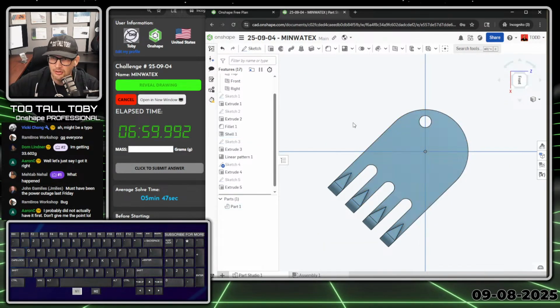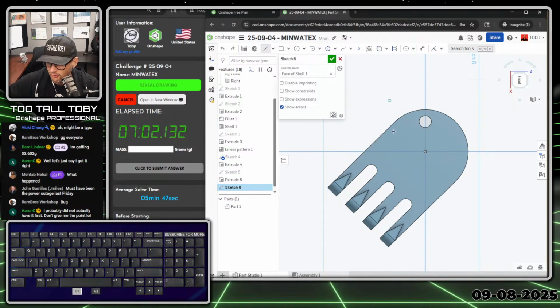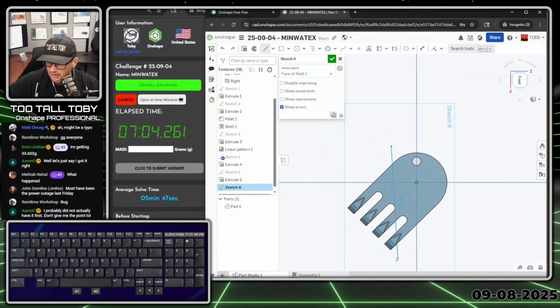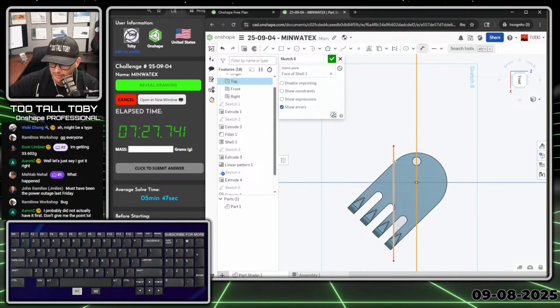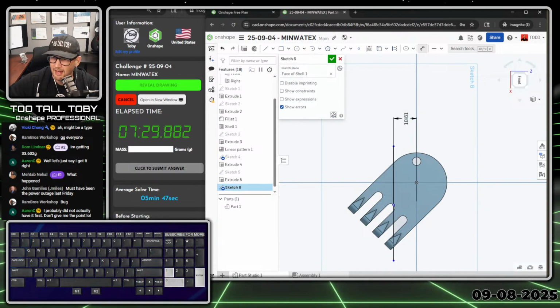this face here and I begin a new sketch and then I create a line there running along that face, then what I can do is take that line and add in a dimension. So the dimension could go here from this plane to this line. And oops, I didn't make the line vertical. Let me click on that line V. Let me click on that line H. I'm very disoriented in this sketch. And then it looks like I picked up a relationship here by accident as well. So let's just get rid of that relationship. I had a midpoint relationship on there by accident. So we'll bring that over at 10.